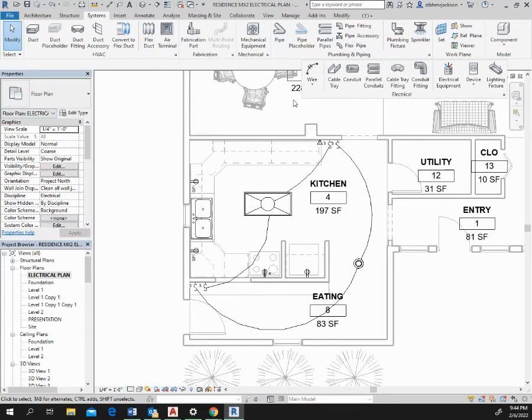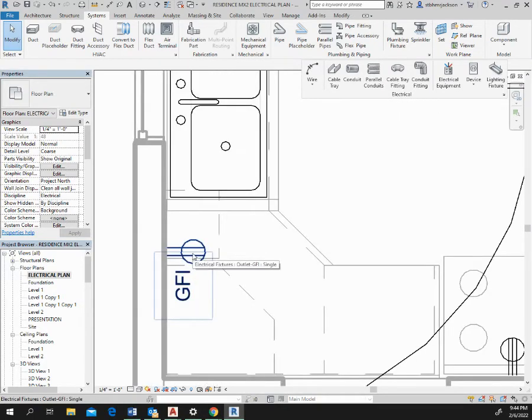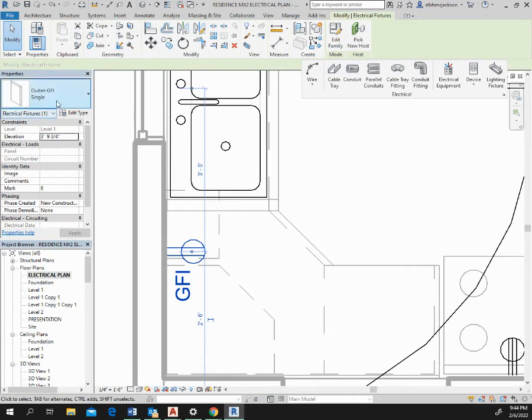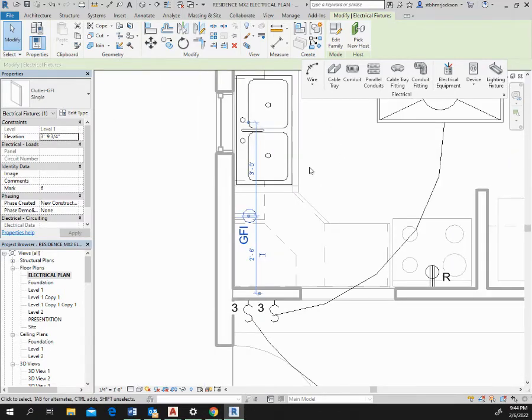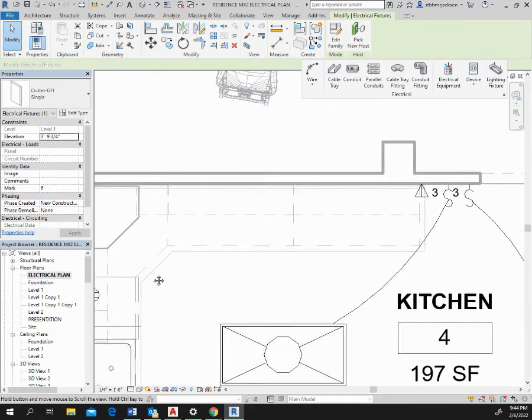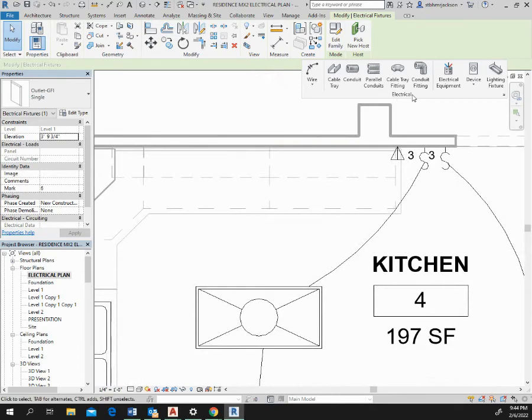And you can also do the same thing with the outlets for your cabinets. They normally sit about the same height as just a GFI. So 3'9" and 3/4, so you can do 3'10", or roughly about, what is that, 46 inches. So about 46 inches. So if you choose an outlet,